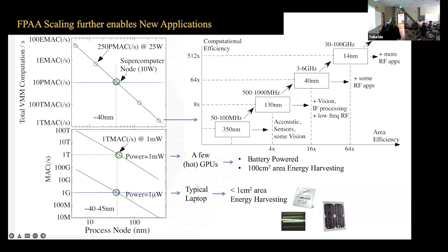Yeah, I could say a lot. There was the conversation on data points and how we look at this. Because we're at 350 nanometer, right? And everyone was like, well, how fast can I go with this? The simple comment is, yeah, you can get about 50, 60 megahertz through in that process node. But as I start scaling things down, 130, 40, you actually have multiple data points, and all of this opens up different questions.